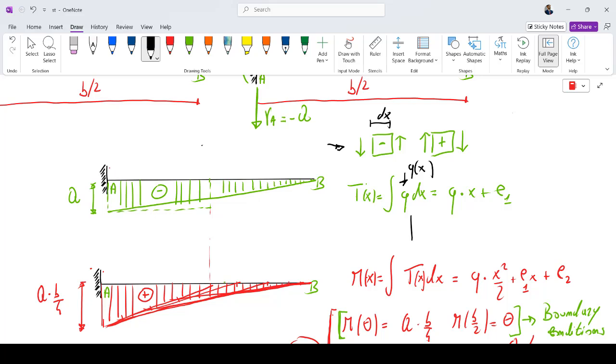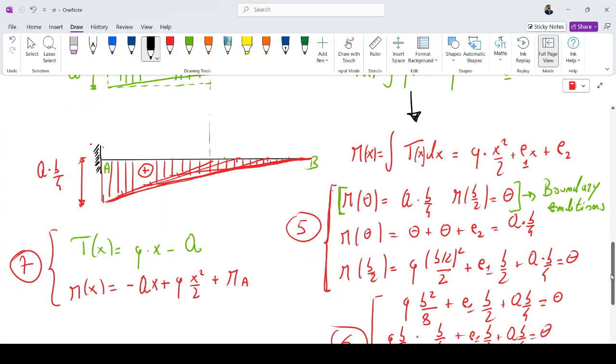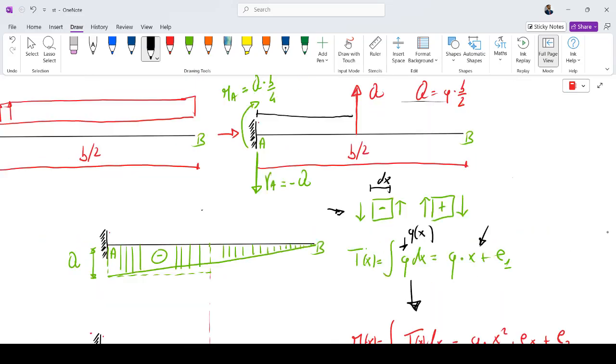So if we move on to the equation of the bending moment, the distribution of bending moment as a function of x, we simply should treat the shear force distribution as a function now of x, because we obtain here a linear equation. If you see the diagram, we can note the trend of this diagram is linear. So it's simple to obtain this diagram.